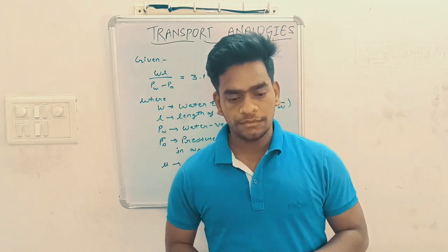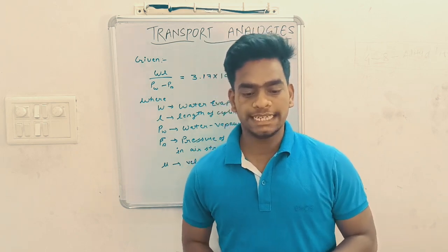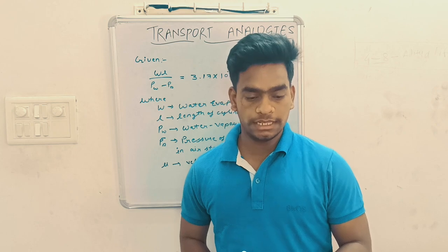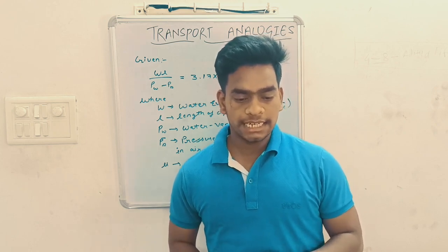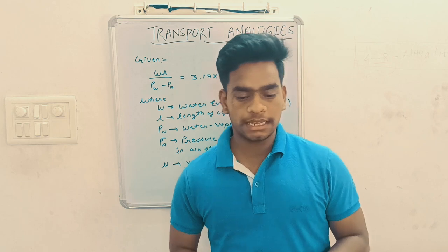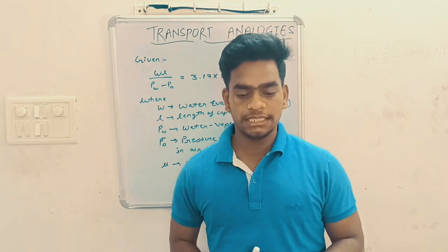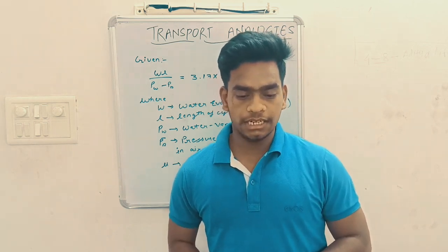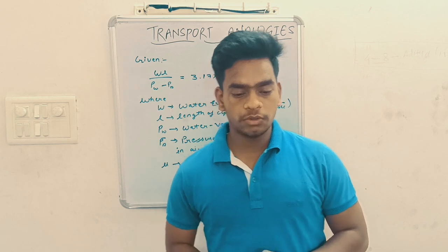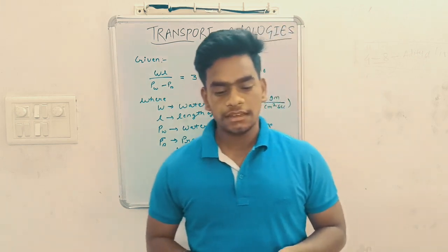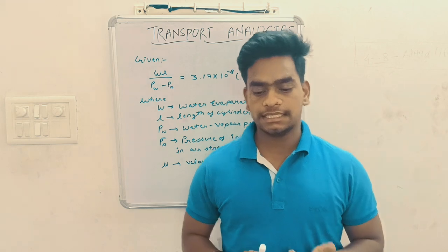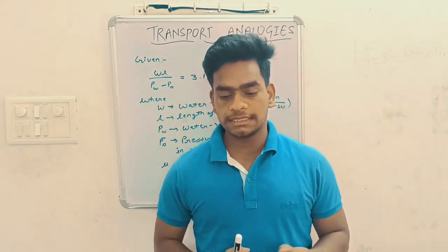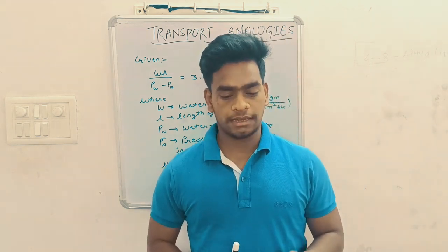We are given physical properties of CO2 like density, viscosity, and diffusivity, the vapor pressure of naphthalene, and it's stated that the partial pressure of naphthalene in the gas is 0, which makes it a dilute system. Our task is to use the same kind of relation from part A to calculate the rate at which naphthalene sublimates and express that as kilogram per hour.